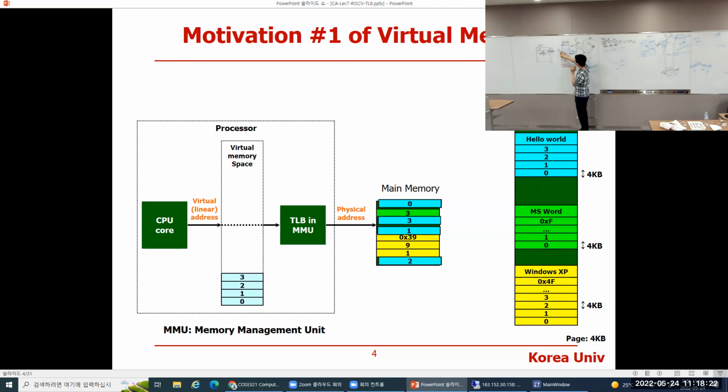So the physical address, probably 64K bytes, then probably F000. Again, the CPU is generating virtual address 0. Then someone should do translation and generate F0, because the first page is located at the top, this 4K byte place. The first code is read from this location and supplied.